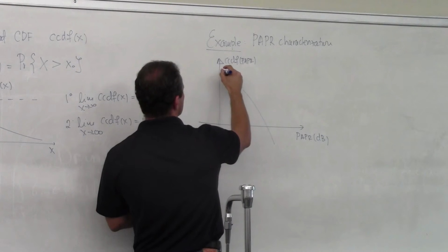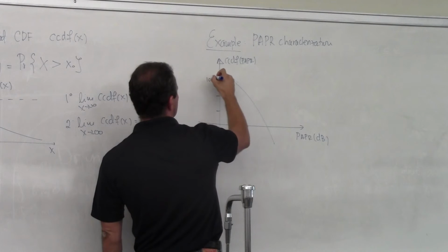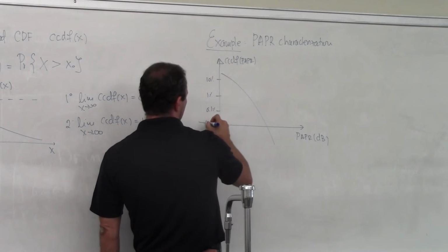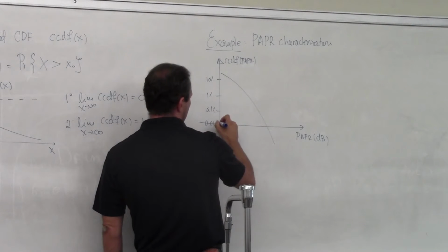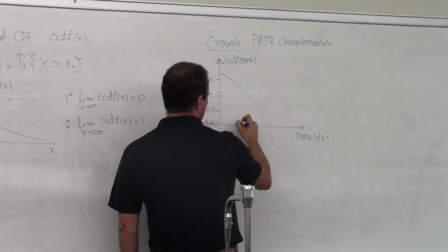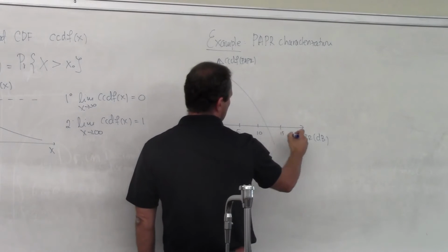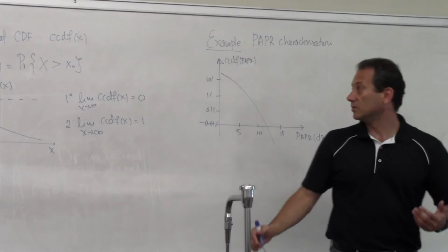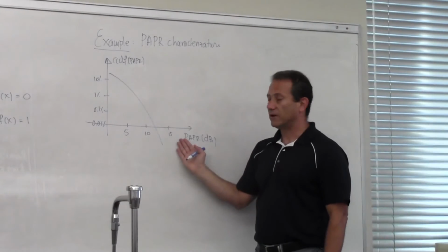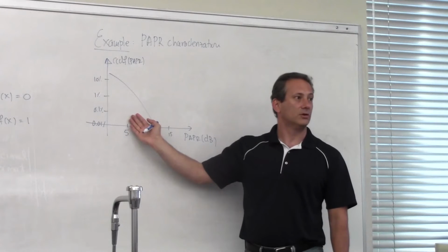Where these are the different thresholds, let's say 10%, 1%, 0.1%, 0.01% and so on. And then here you get some values. Let me just give the numbers. So let's say this is 5, 10, 15, and so on. So this would be a curve that would characterize the waveform, telling us peak to average power ratio in dBs, and what is the probability of exceeding the particular peak to average power ratio.